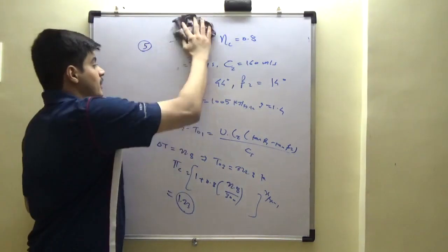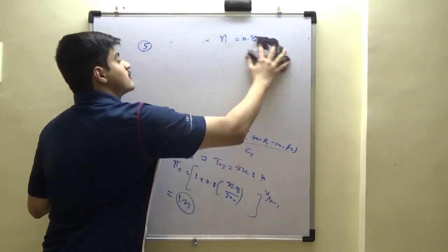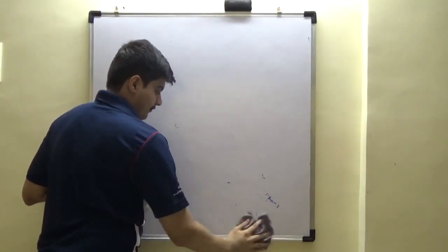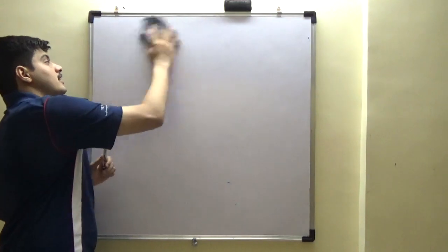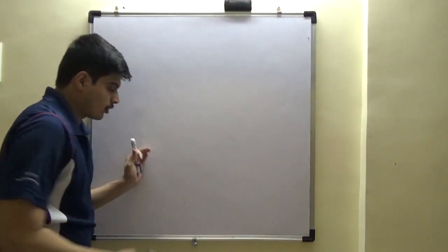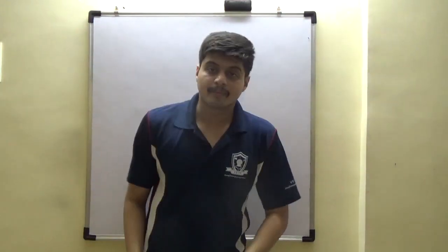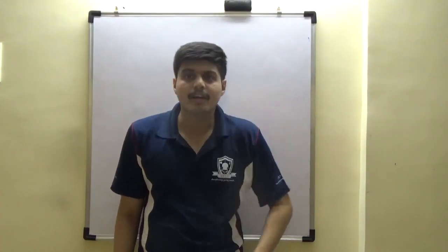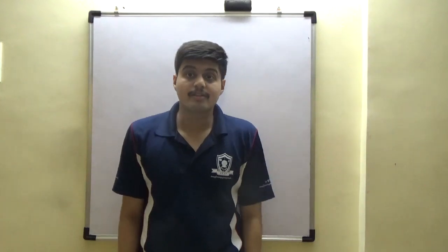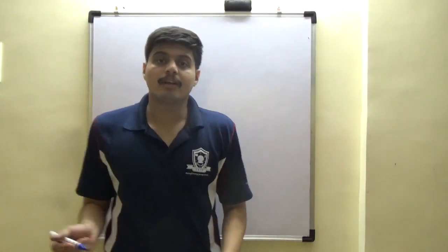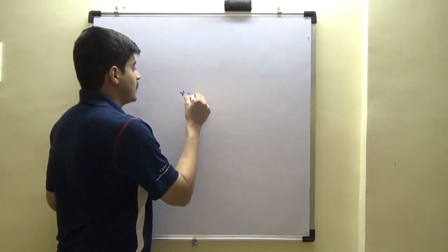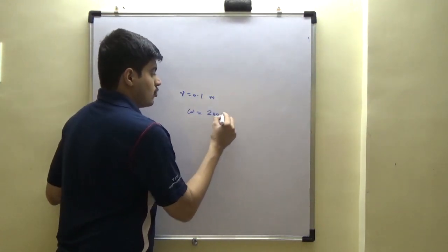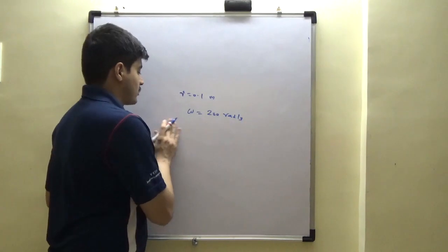You may feel this is very, very low and your observation is very correct. Now we have to guess ourselves why. This is not asked in any question, but this is your own introspection to get more flavor. We said blade speed is 200 meter per second, which is quite high. It's a decent enough velocity, right? If typical radius is say 0.1 meter, omega is 200 rad per second.